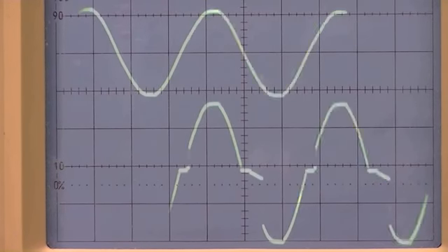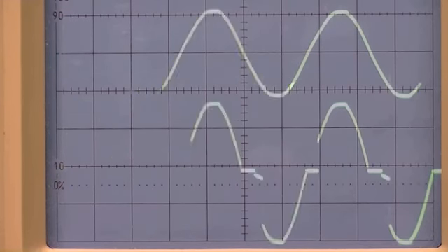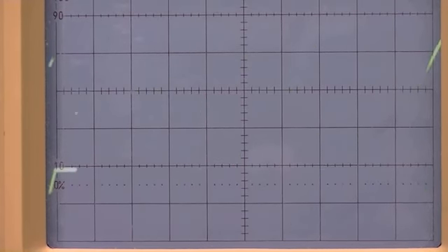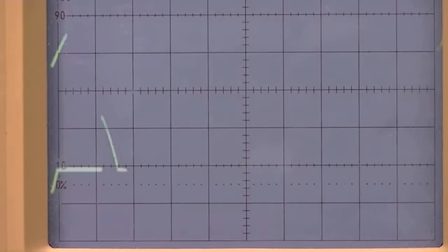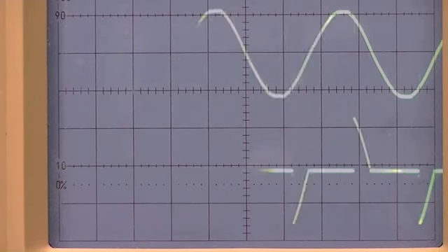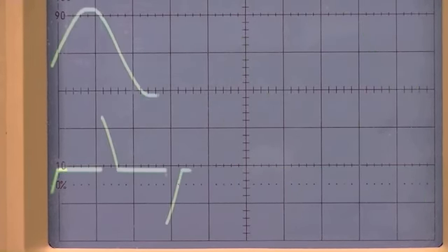Let's cut it on full power and get it up, and as you measure the temperature and as you approach the desired temperature that you want, you begin to electronically cut back on the amount of energy being delivered to the heater. And when it reaches the point that you want, you just put in enough energy to keep the device at a fixed temperature without overshooting and having it go down. This also saves a lot of energy.